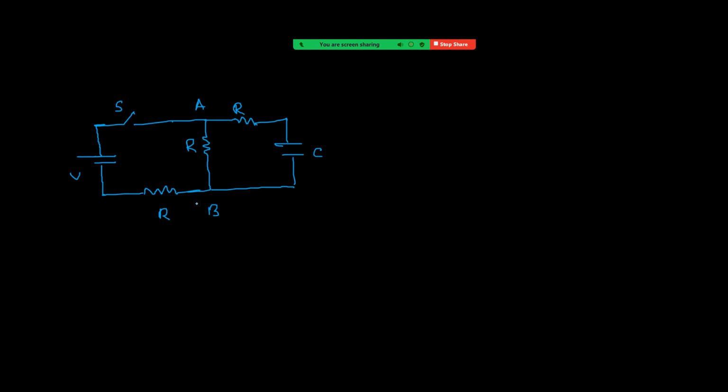So we have to find a charge on capacitor as a function of time. So Q as a function of time, right? See what we can do here. So we can simplify like this. This is equal to maximum charge into 1 minus e power minus t by tau, where tau is known as time constant. Okay. Now, first focus like this. What is maximum charge?